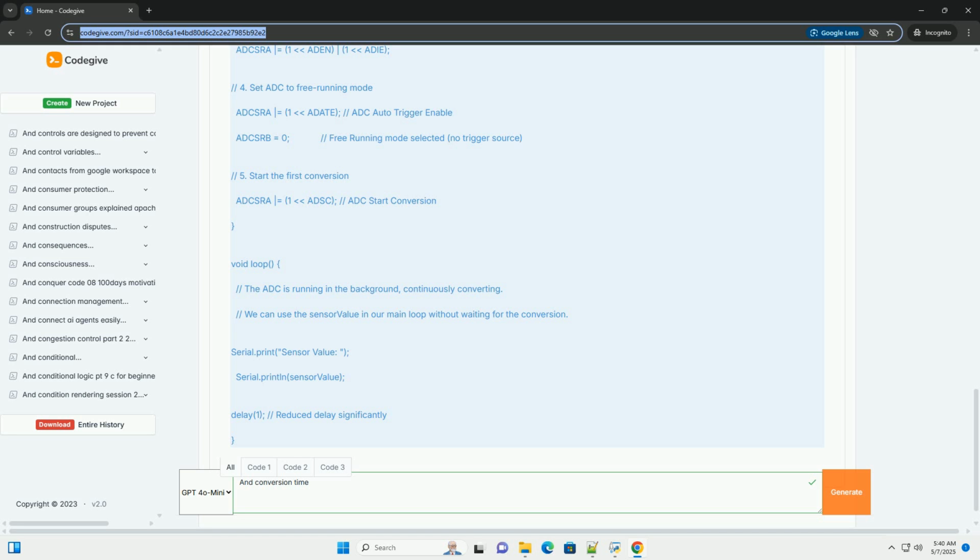Clock frequency: the ADC typically relies on a clock signal to drive the conversion process. A higher clock frequency generally results in faster conversion times. However, the clock frequency is often limited by the ADC specifications and the settling time of internal circuitry, comparators, DACs.